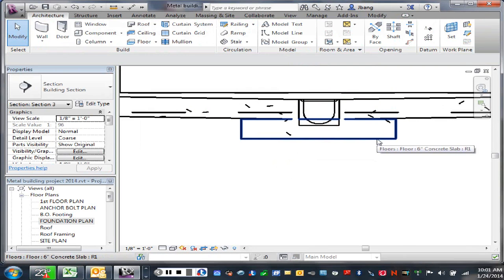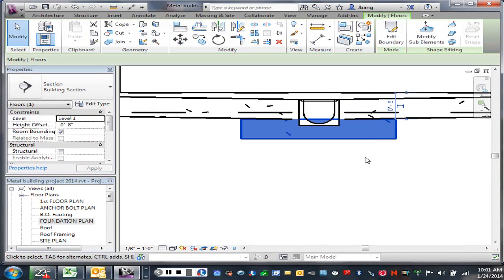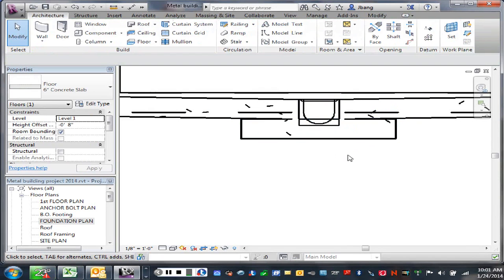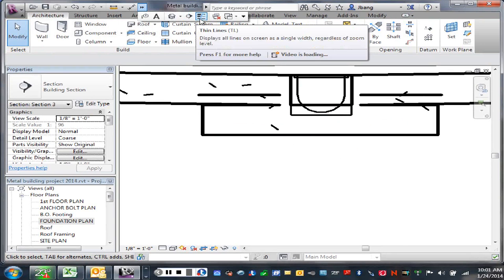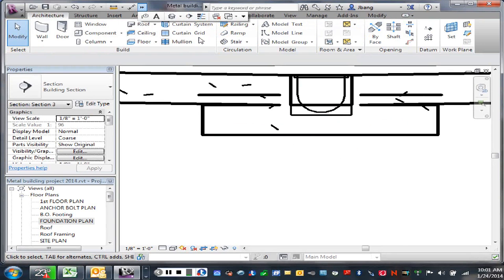Is it important to make it bigger than the drain hole itself? Yeah, the concrete would have to go down and around it, so the whole drain is encased. Okay, so it should go past the drain, basically, is what I'm asking. Any specific distance, how far, or a couple inches? I would say if the slab is 6 inches, you'd want to go 6 inches outside of it on each side. That'd be fine, sure.